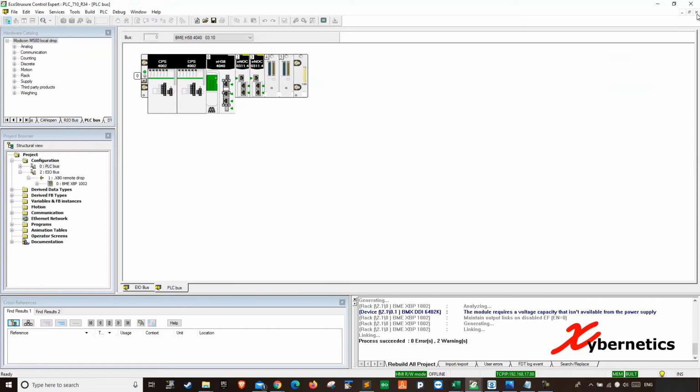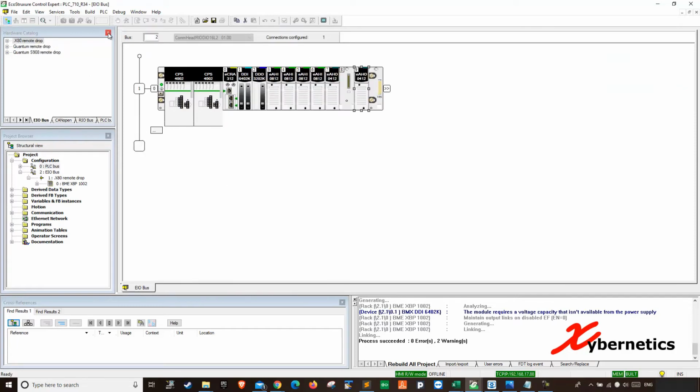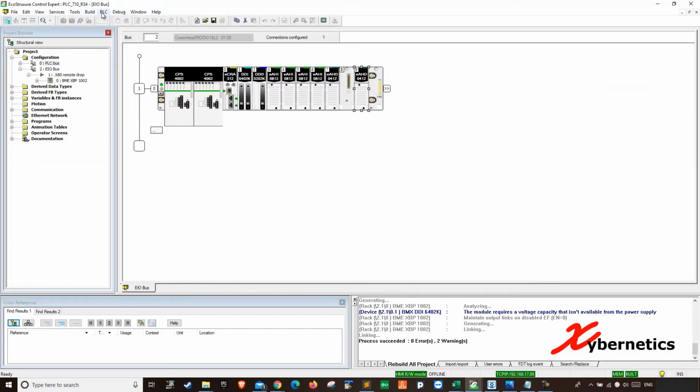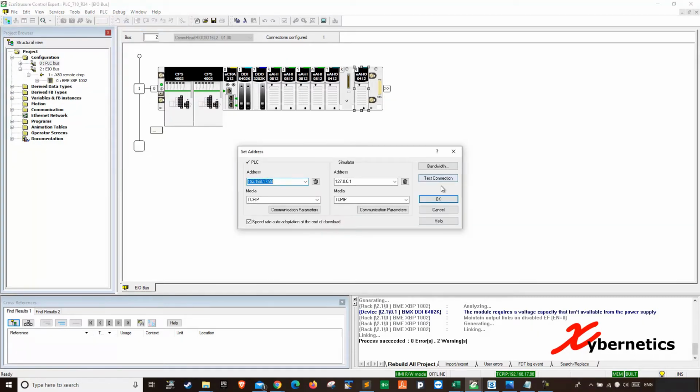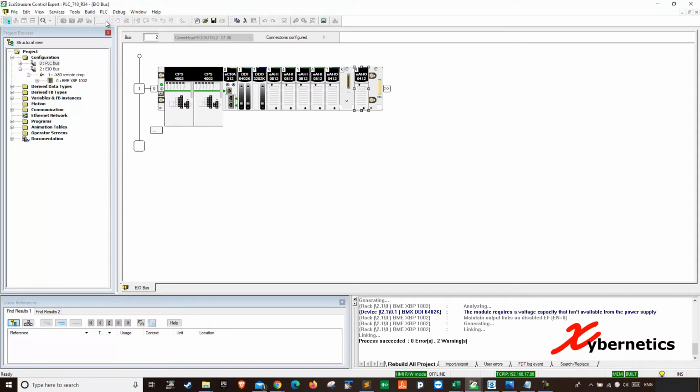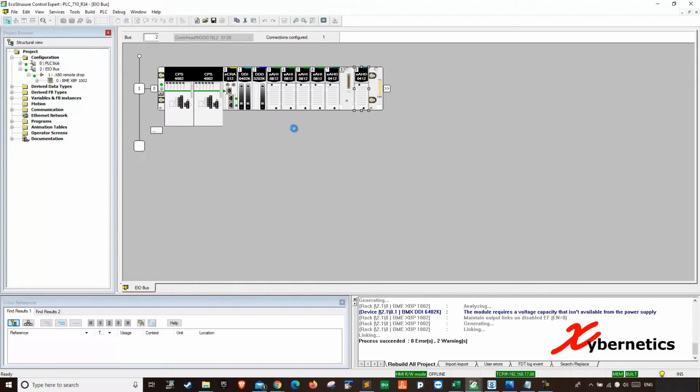So I'm going to close the CPU section. So going back here, if I go PLC, that's where you put in your address here. So okay, and then now if this is good, you go connect. After a while, it will connect, and if you look at this setting here, you can see 9 is not configured. If it's configured correctly, this will show as white. Okay, so right now it's not configured, so let's get started.